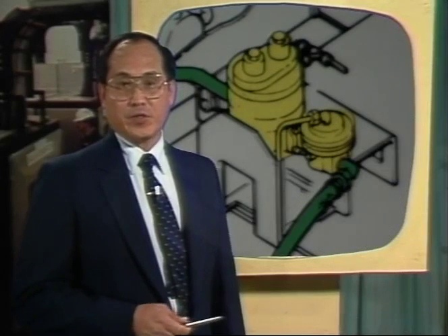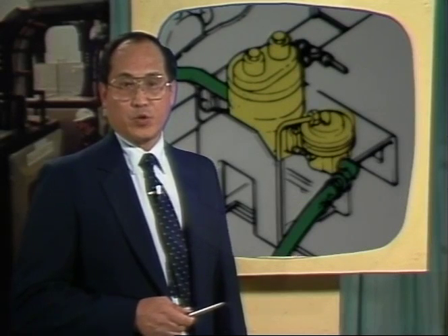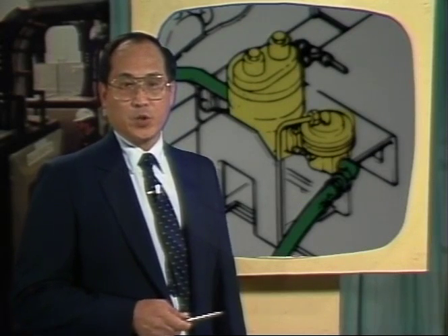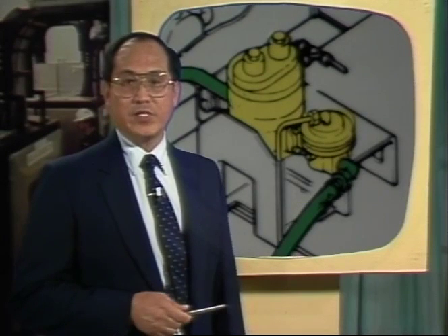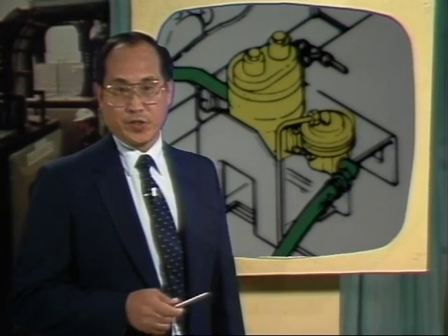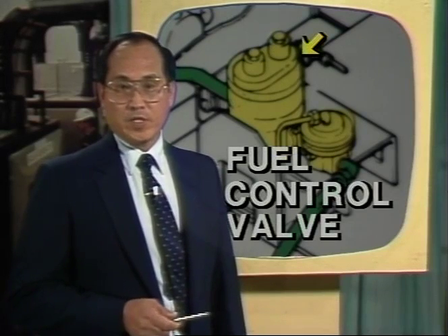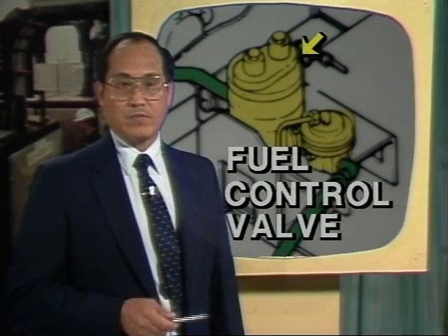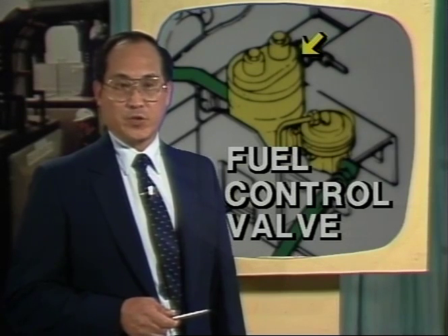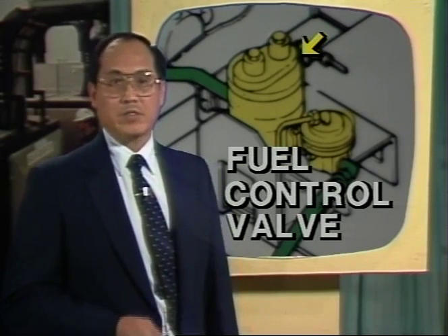Gas turbine engines require an exact proportioning of fuel and air to achieve a smooth acceleration and to ensure that the engine doesn't go into surge during start. The fuel control valve, located downstream of the secondary fuel valve, functions to provide this critical fuel-air balance.